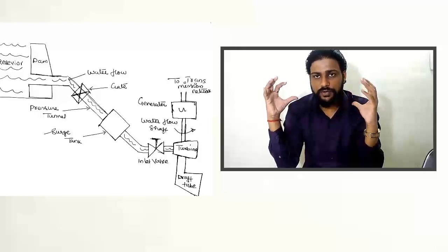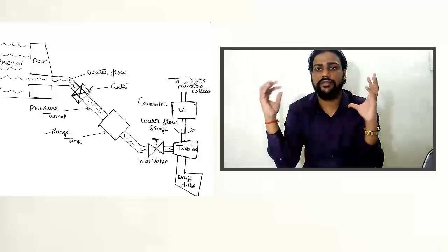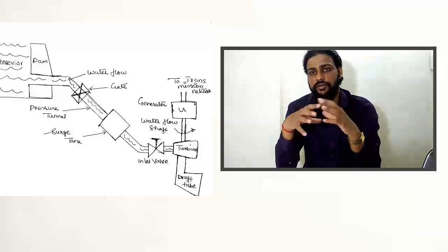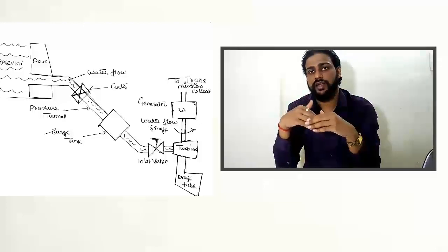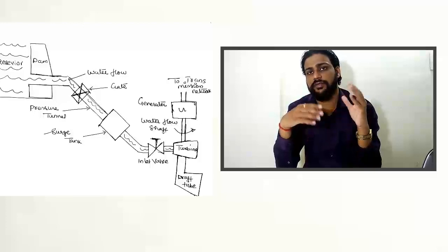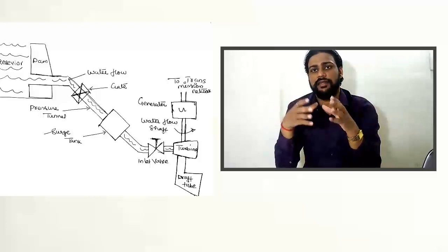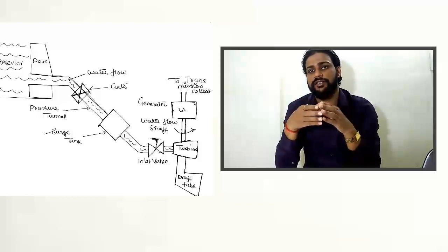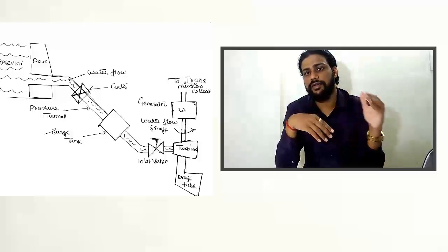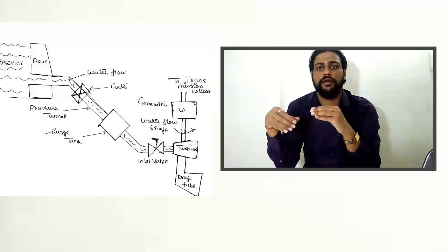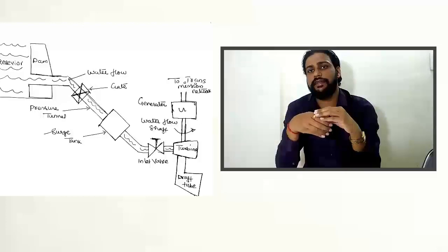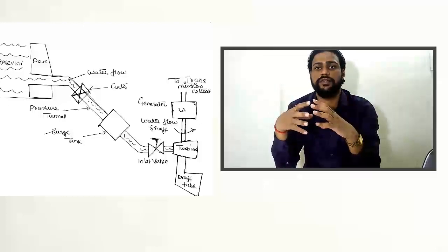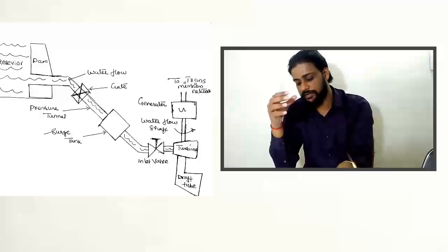So the full amount of water will be made to flow over the turbine blades, which will cause a kind of reaction, which will cause the turbine blades to rotate. The Pelton wheel or impulse turbines are used where the head is high. Whenever the head is high, it is possible to have a large amount of kinetic energy. While if the head is low, like the dam height is less, it's possible to store a large amount of water, but since the length of the tube carrying the water from the dam to the turbine is less, it's not possible to get that amount of kinetic energy. So you will need some kind of impulse effect and a reaction effect by flowing a large amount of water over the turbine to produce a large amount of electricity.